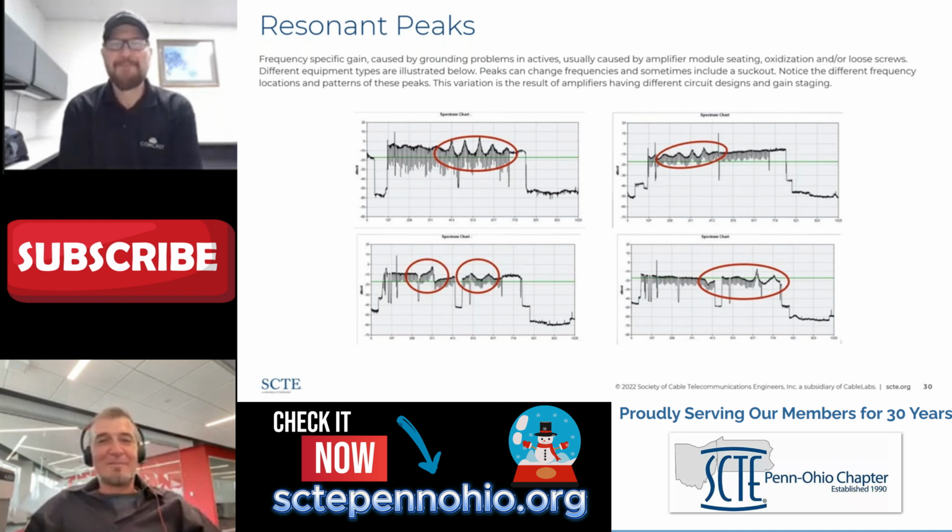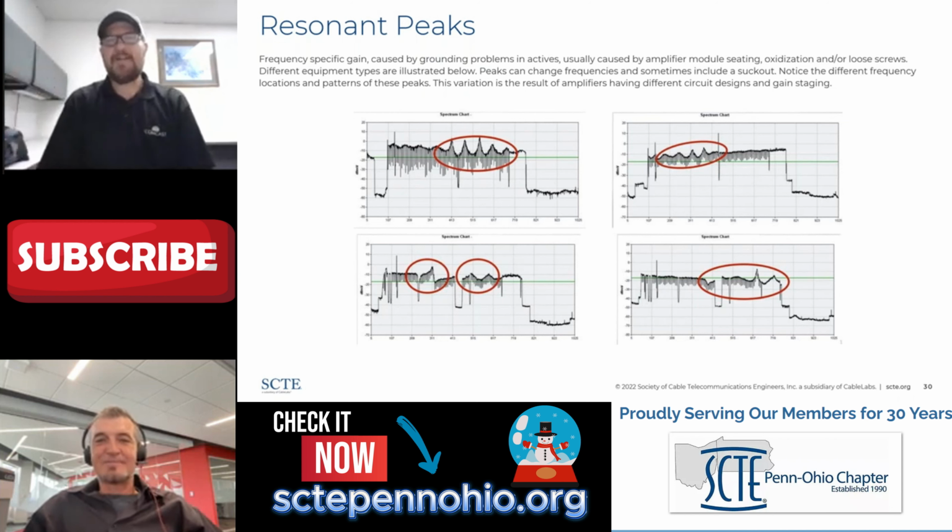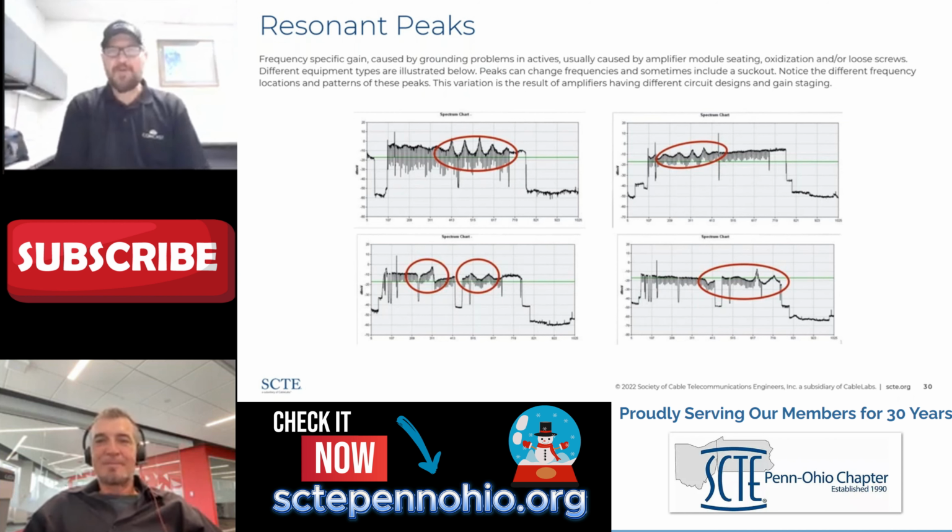You're the dude. So some of the things that we do that we probably shouldn't is we can look at our full band captures and say, hey, all of the modems or full band capable devices after this amplifier all share a resonant peak. So how do I fix it? Well, I can go open the pedestal and kick the housing and it'll probably go away. Or I can take my layup stick off the truck and give the amplifier a good whack on its aerial, and the resonant peak will probably go away for a while.